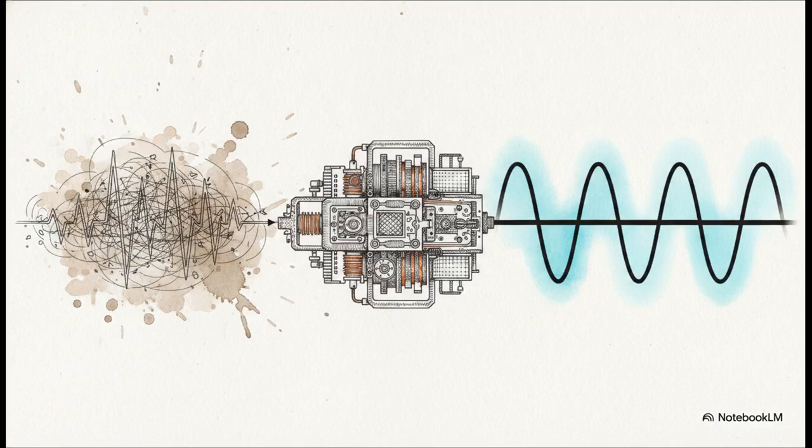So you might be wondering, why is that third step, signal conditioning, so necessary? Like, why can't we just take the raw electrical conversion and run with it? Well, raw physical data translated into electricity usually gives us incredibly weak signals. Sometimes we're talking just a few millivolts. Not to mention, real-world industrial environments are incredibly messy. They introduce a ton of stray electromagnetic interference and electrical noise that has to be filtered out. And finally, computer inputs require highly specific voltage or current formats to be read accurately at all. So signal conditioning takes that raw, weak, noisy pulse and amplifies, filters, and formats it into a robust, readable signal.